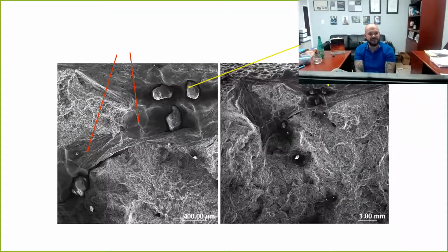It's the only explanation for why there would be grains of sand in a casting, because even in aluminum, there's an order of magnitude density difference between silica sand and aluminum, right? Three orders of magnitude when we get to the ferrous alloys. So there's no explanation as to why our customer machines into a casting and finds a patch of sand, until we realized that that sand was stuck in these oxide films. And now when we go back to the slide, you'll notice as clear as day that we've got a bag of oxides with grains of sand in it.